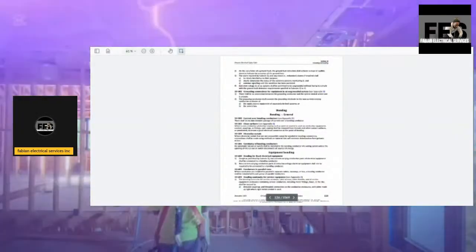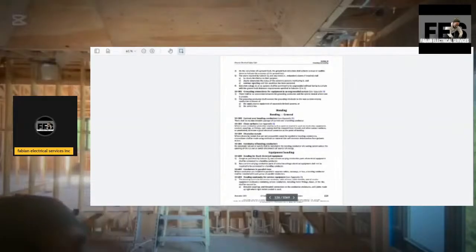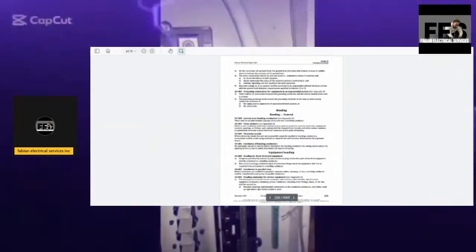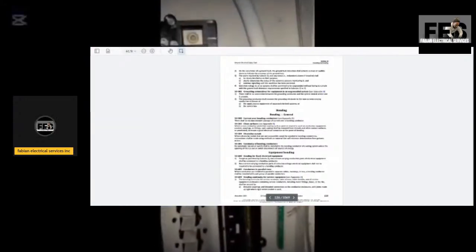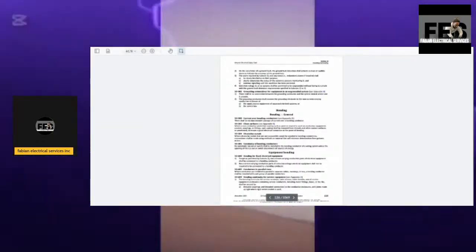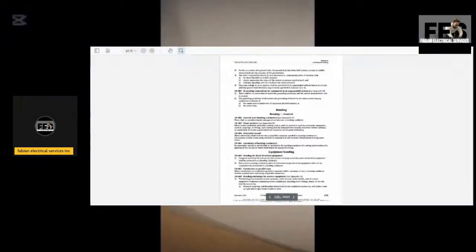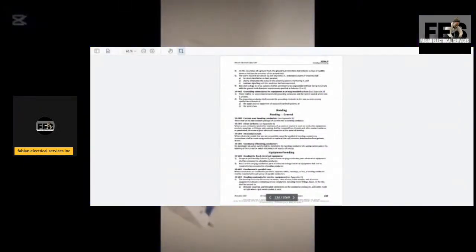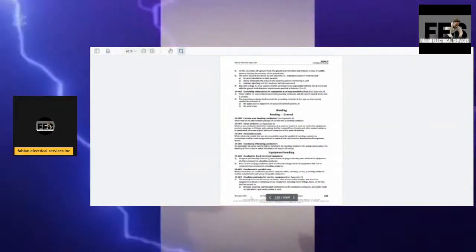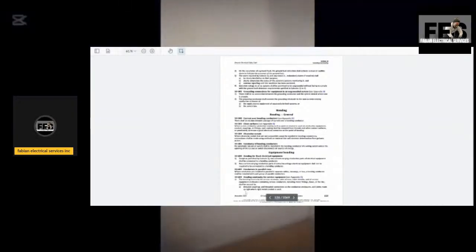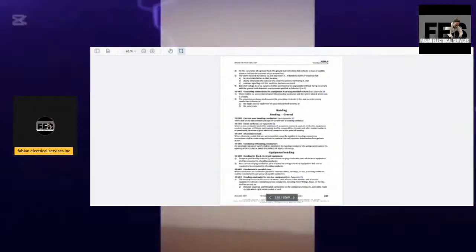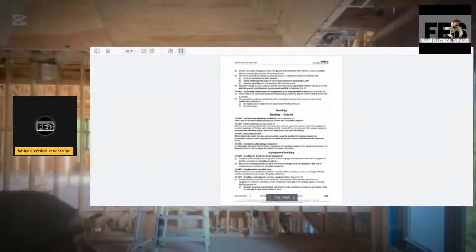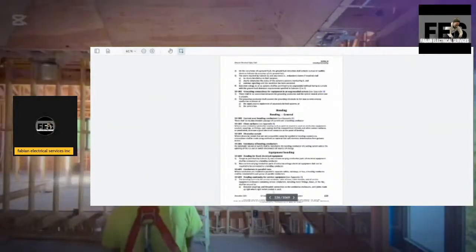Bonding continuity for service equipment. The bonding continuity for service raceways, cables, armored cable, sheaths, and all service equipment enclosures containing service conductors, including meter fittings, boxes, or the like, shall be assured by threaded couplings and threaded connections to the conductive enclosure, with joints made up tight where rigid metal conduit is used.